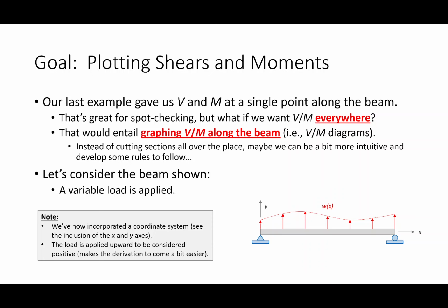Cut a section here, get a shear and moment. Cut a section here, get a shear and moment. Cut a section here, get a shear and moment. As an engineer, I need to know what's the worst case shear and moment on the beam overall. And really what I need to know are the shears and moments everywhere.